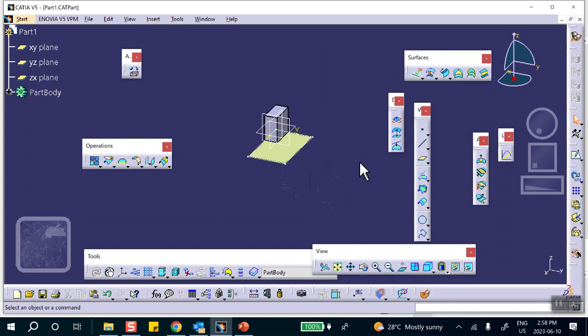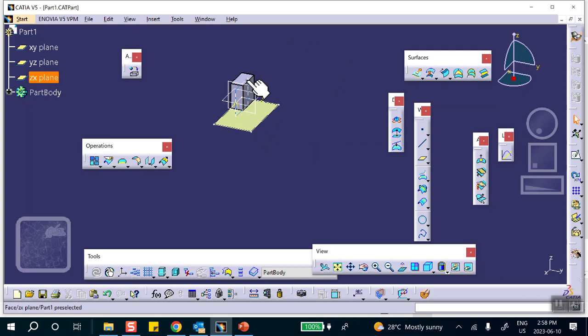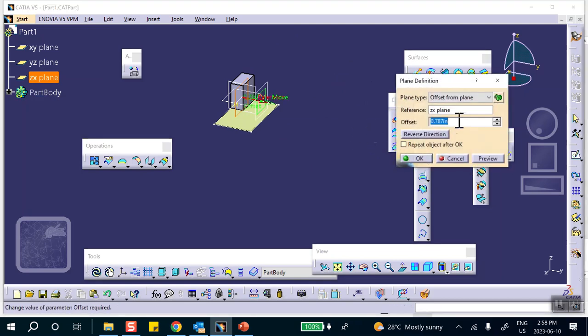And there are different ways of doing it. It's entirely up to you. So you can make a circle in space, no problem. Or you can do it a different way. For example, you can create a plane parallel to that, at distance 1.5.